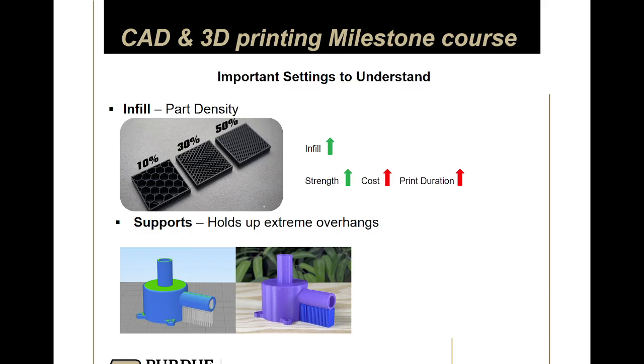It's less work for me, a little bit less print time. And sometimes if your parts are super, super small and they have supports around them and you break the supports off, you're going to break your part too. So that's something to keep in mind as well. Minimizing supports is ideal, especially because you're designing the part. But if it's not avoidable, then sometimes you've got to use them.